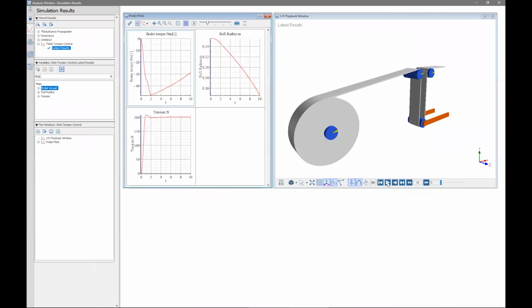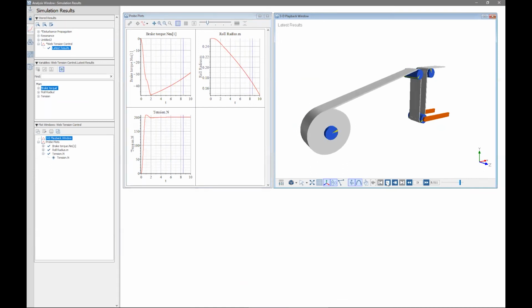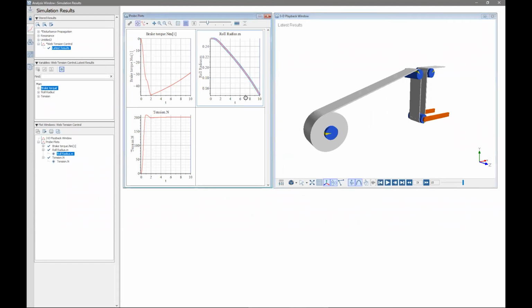And here's the situation, this being the target. After the initial ramp up, I want to keep the tension steady, although material is being removed from the unwind roll. So it has less inertia as time passes, and it also loses radius, as you can see in this plot of the radius of the roll. And this is the brake tension that is being applied to the drum to keep the tension steady.